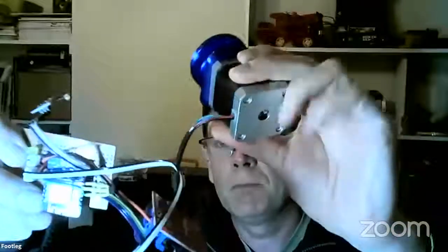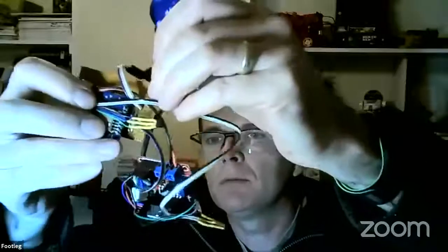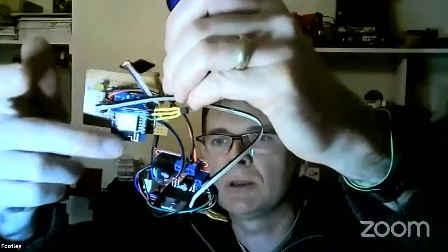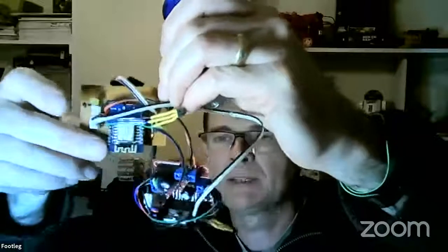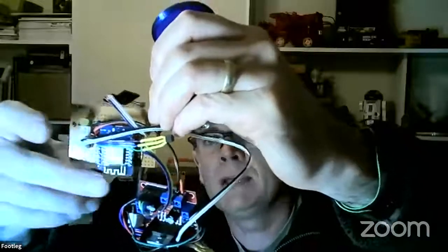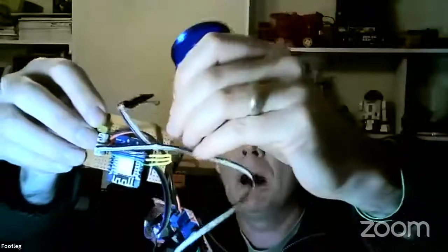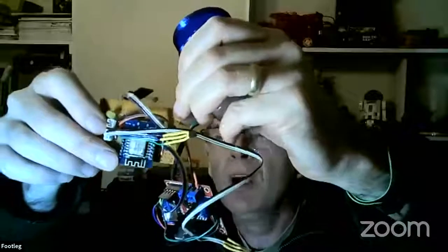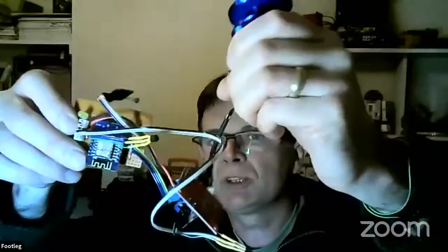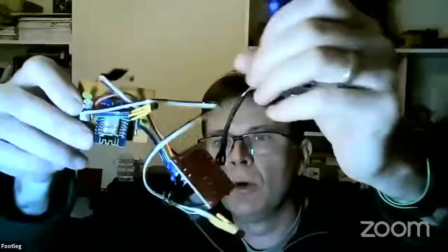Now, there's a few power considerations here. The stepper motor needs 6 volts to power it. The D1 board, which is soldered onto this, is the kind of Wi-Fi enabled microcontroller, that has a 5 volt input, and it drops that down to 3.3 volts. You can power it directly off 3.3 if you want, but because this board that I used had a 5 volt input, I thought all I've got to do is I need 6 volts for the stepper motor and the motor driver, but 5 volts for the electronics. And let me jump back to the screen share.